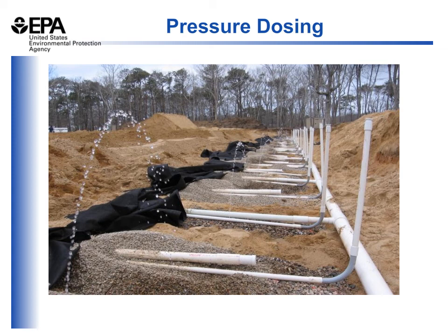This is the far end of the leaching trench from where the water enters it, and it's showing that water is flowing under pressure at the far end, which also implies that it's flowing out into the trench along its whole length. As you see here, there's a series of larger PVC pipes next to the pressure dosing lines. These are air vents that are installed separately from the pressure dose lines.